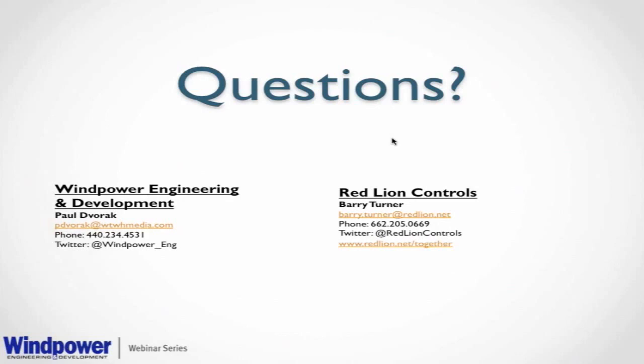Peter asked this question. Are you using multi-mode fiber with ST, SC, or LC connectors? Yes. We see people use multi-mode on all those different connectors, for sure. The main thing is if you have a short connection, then multimode is going to be what you want to use, because multimode uses an LED instead of a laser, so we want to use that for shorter runs. We want to use a laser type connector or a single mode module when we have a longer distance, so about 2 kilometers.